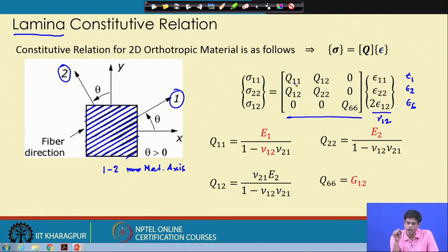That is not required right now. Here I have depicted the constitutive matrix in terms of Q. Instead of C, which we derived for the 3D constitutive matrix, if we impose the plane stress condition, then you get the Q and Qij's. So that we will learn later.